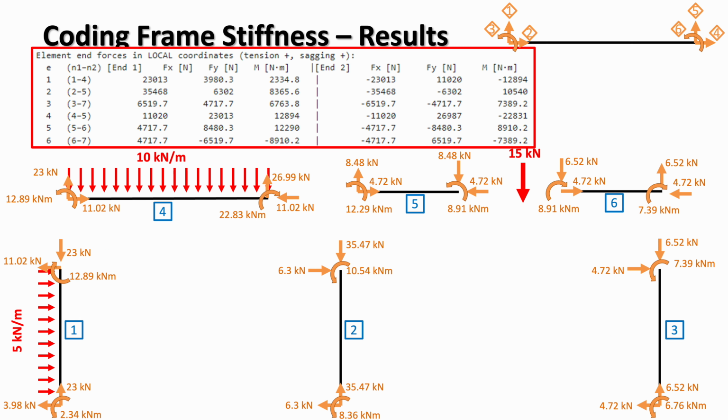On this very cluttered slide, we are looking at the internal forces in every element of the frame. These are expressed in the local coordinates using the same sign convention we defined earlier in the course, which is at the top right of the slide. So, as I said, all forces and moments shown on the diagrams have been drawn in their correct physical directions. That means that whenever a computation produced a negative value, the arrow has been flipped to match the true internal action of the member.